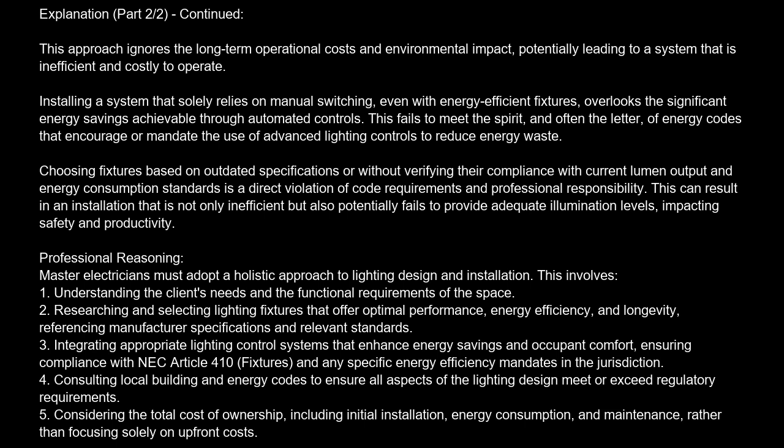Installing a system that solely relies on manual switching, even with energy-efficient fixtures, overlooks the significant energy savings achievable through automated controls. This fails to meet the spirit, and often the letter, of energy codes that encourage or mandate the use of advanced lighting controls to reduce energy waste.